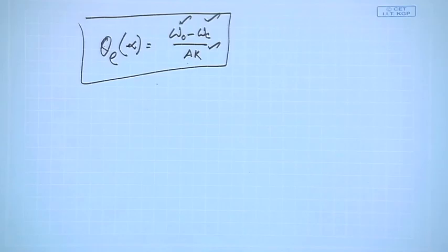The attenuation should be the cos of that phase error term. So, as long as we can set omega 0 and omega c, meaning we now know how to design all this, we know how much phase shift will be there with that kind of loop filter.